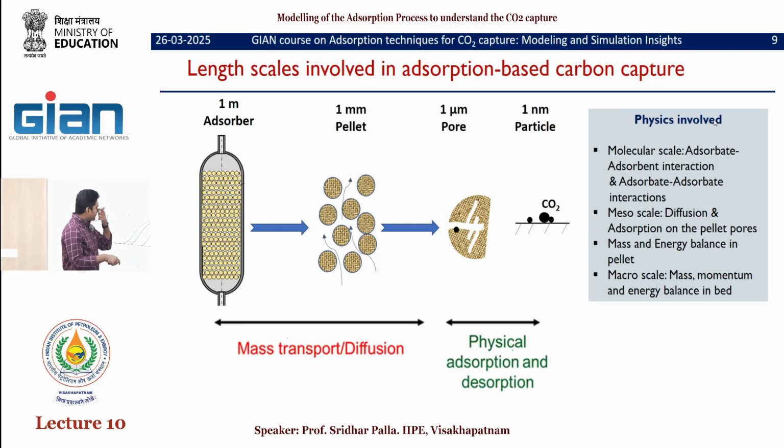If we carefully observe, the adsorption is happening here, and gas particles will diffuse through the macropores of this particle pellet. Then there are micropores inside the particle, and also gas is diffusing through the voids of the bed.